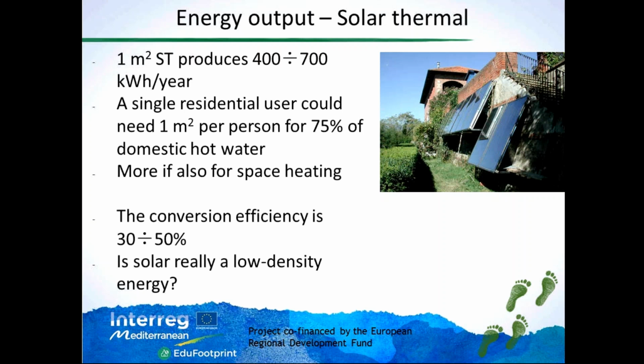That is why a very good application of solar thermal is the production of domestic hot water, because in this case temperatures needed are quite limited. And also if you have to use, let's say, solar thermal for space heating needs, then it would be better if it's possible to combine solar thermal with some low temperature heating, right? Like for instance, radiant floors or something like that.